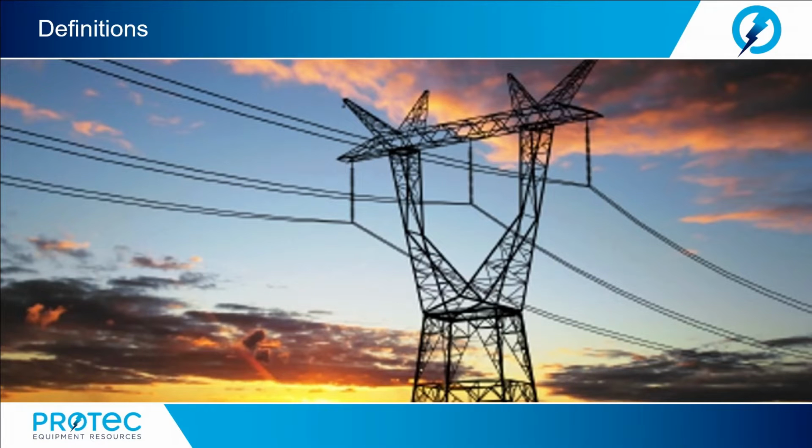A core definition that establishes a bright line threshold that includes all facilities operated at or above 100 kV, and a list of configurations that are deemed to be, regardless of their voltage rating, included or excluded from the bulk electric system. Facilities that are deemed to be included in the bulk electric system are subject to compliance with NERC reliability standards.